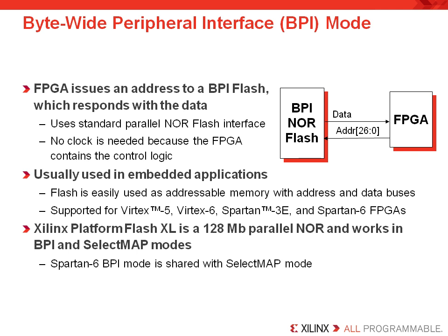In an embedded application, such as one targeting the PowerPC or a MicroBlaze processor, the platform flash can store the application code, then after configuring, the FPGA can transfer the software from the platform flash to an off-chip memory, usually an SDRAM. The software code is then executed from that external SDRAM. FPGAs support two versions of BPI configuration. BPI Up starts configuring the FPGA from flash address 0 and automatically increments the memory addresses. This is the most popular mode and most likely the primary mode to be supported in future FPGAs.